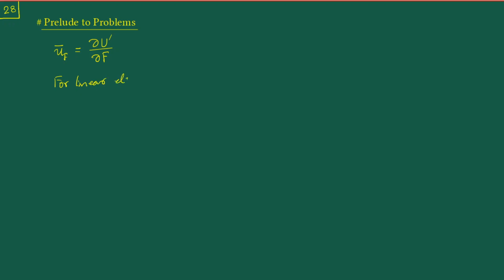we had mentioned that this U dash is equal to U, which is the strain energy. And mostly we will be dealing with the kind of problems which are made up of these linear elastic materials, in fact linear elastic isotropic materials. So we won't be bothered too much with this distinction between U dash and U, but we will also be solving at least one illustrative example involving a nonlinear material, for which we'll have to go down the route of using the U dash.